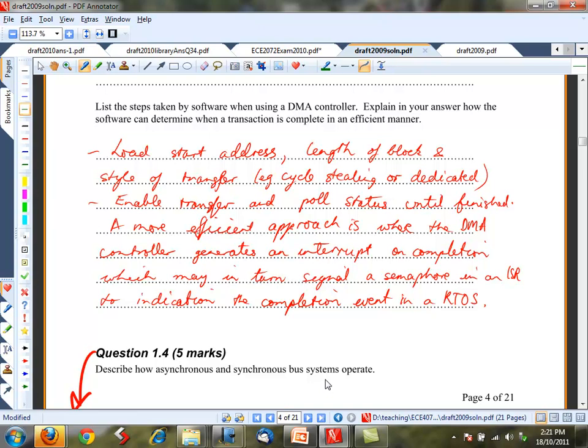What's the big difference? If I give you an asynchronous logic circuit, it might be an RS latch, and I give you a synchronous one, it might be a counter. What's the difference between them fundamentally? The synchronous one changes on clock pulses. Yes. So you have a clock in the synchronous one dictating when things happen, and in the asynchronous you don't.